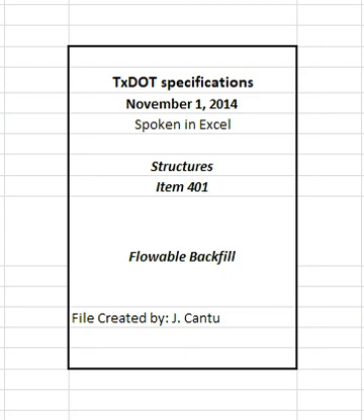Furnish a mix meeting the requirements of Table 2 unless otherwise shown on the plans. Table 2. Flowable fill mix design requirements. See table in specifications. 1. Average of 2 specimens. 2. Mixture must not segregate. Mix the flowable fill using a central mixed concrete plant, ready mix concrete truck, pug mill,